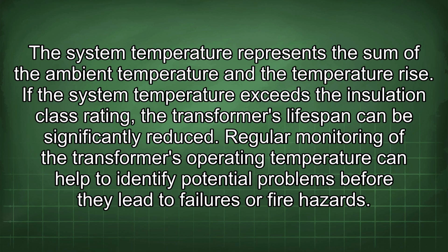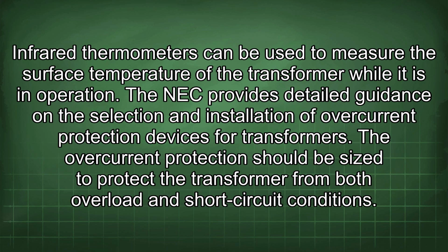Regular monitoring of the transformer's operating temperature can help to identify potential problems before they lead to failures or fire hazards. Infrared thermometers can be used to measure the surface temperature of the transformer while it is in operation.